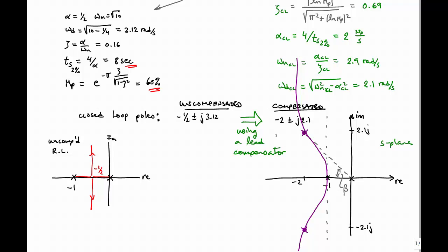And notice that in doing so, the trajectory, or the asymptotes that I want, are still going to be at plus and minus 90 degrees. So I don't fundamentally want to change the number of poles minus the number of zeros. I want to maintain that as 2.